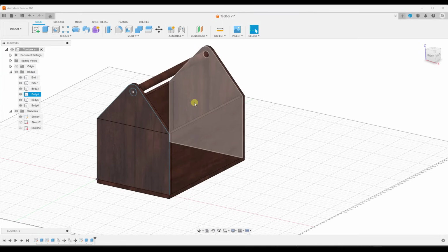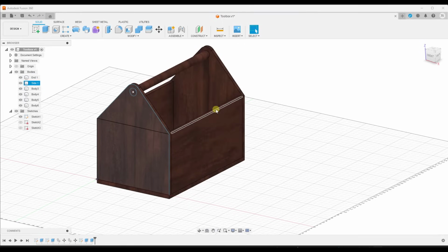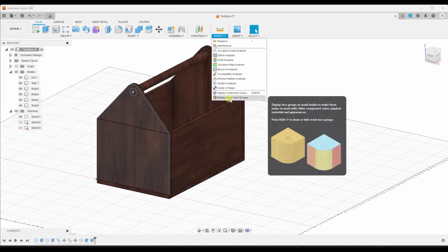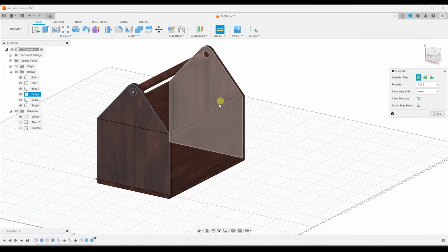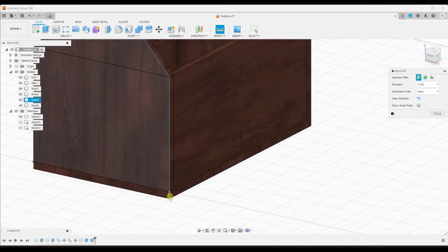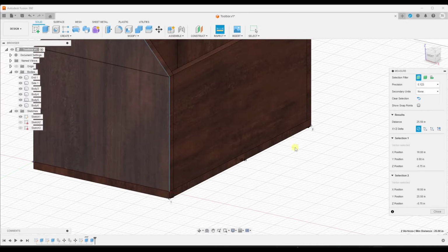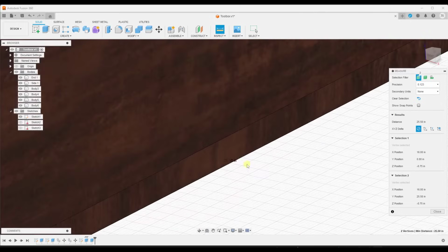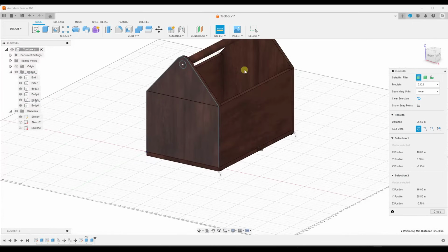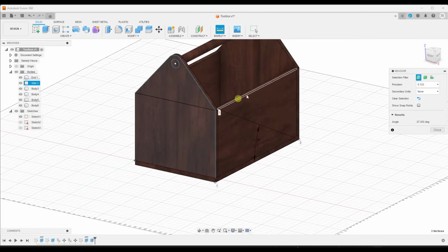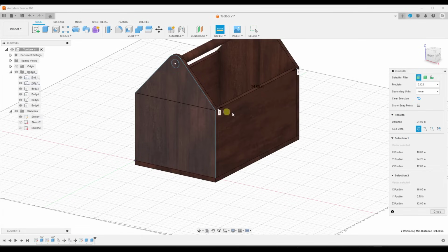And so we'll talk about creating plans in a future video, but if you ever want to come in here and measure a length, you can use the inspect function. And in the inspect function, notice that there's a ton of stuff that we can inspect, but in this case, we want to click on the measure option. What that's going to do is let us mouse over different things and select them, right? So say I wanted to measure between this corner point and this corner point, I can click in here. Notice how this is going to show me a distance. It'll actually tell you the distance over here as well. So if you do want to come in here and actually measure, like, okay, what's the actual dimension from this point to this point, you can use that tool in order to figure out those measurements really quickly.